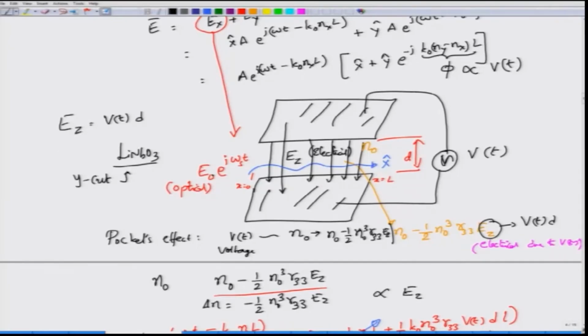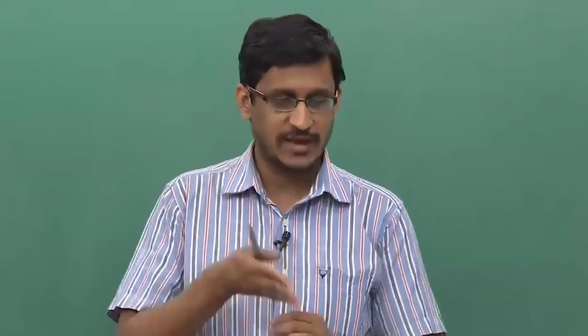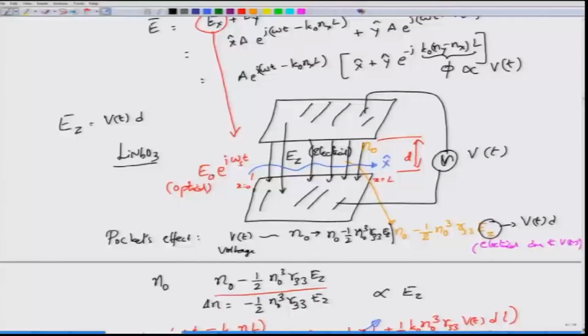In fact, all optical modulators are made out of lithium niobate. Commercial optical modulators operating for optical communications are made out of lithium niobate. They are all usually Y cut, and you have an X propagating wave. But please remember, what is Y cut, X cut, and Z cut is the crystal frame of reference, not our frame of reference. So, one has to perform some crystallographic studies in order to locate the principal planes and then cut your crystal along that particular plane. This is the Y principal plane that you will have to locate and then cut along.